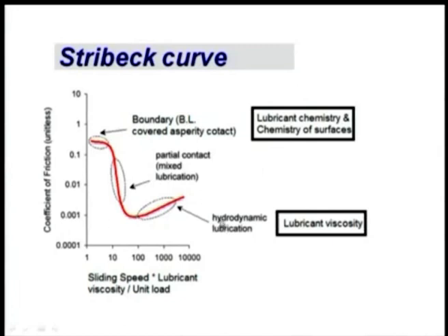elastohydrodynamic lubrication, where basically the mechanism will be hydrodynamic lubrication, but along with that we will be considering elastic deformation of the surface and the viscosity thickening effect that will increase the load carrying capacity. In fact, almost every element needs to have an elastohydrodynamic lubrication mechanism if we are really worried about the cost, if we are worried about optimum performance. Optimum performance happens at that point.